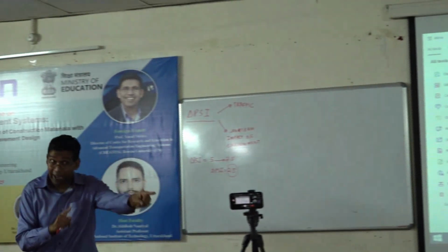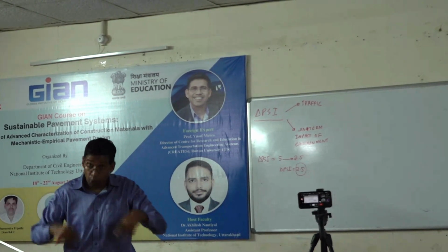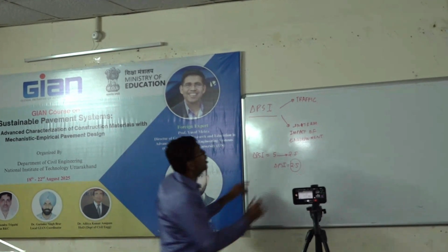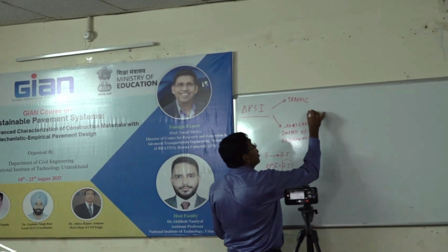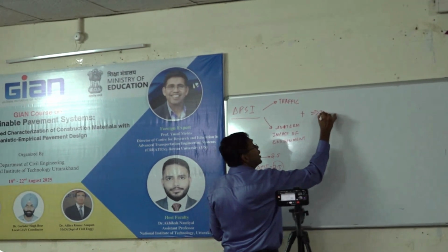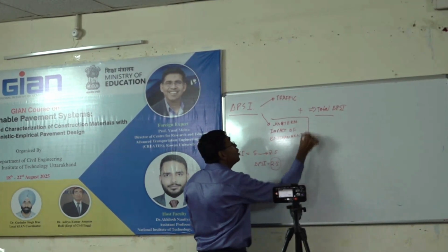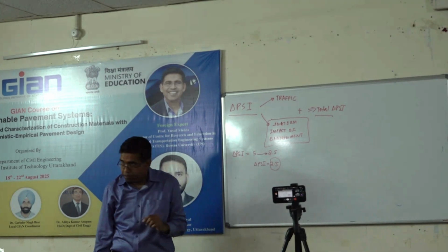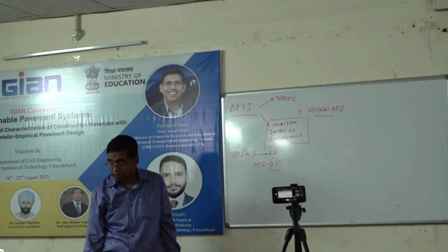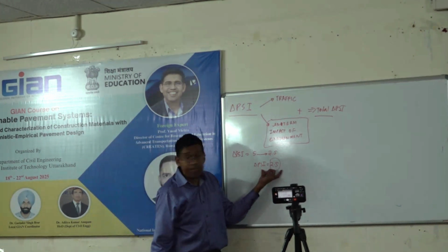Short term is due to subgrade. I just did the short term due to subgrade for the 1 year, right? But the long term, over a long period of time, without me having any traffic, there will be a loss. So the summation of these two is the total delta PSI. So this is one way to account for the long-term impact of environment. Swelling, frost heave, got it? So I wanted to bring that up. But it is already embedded in the 2.5.